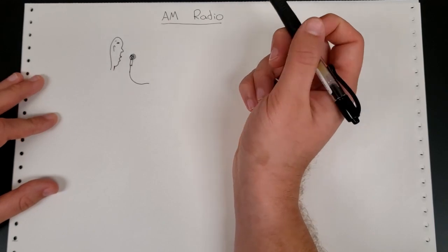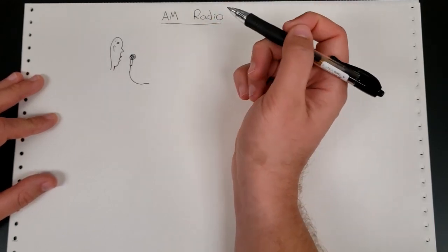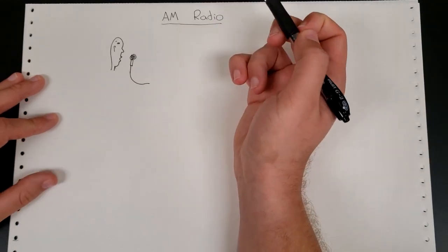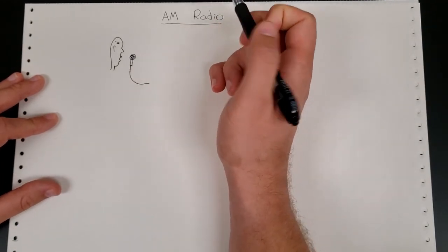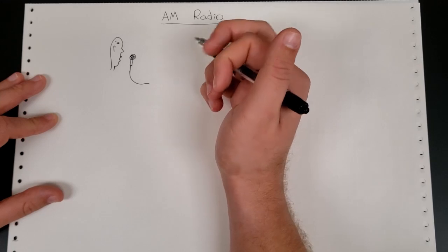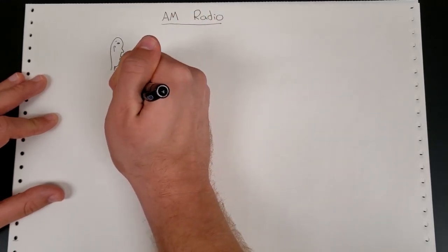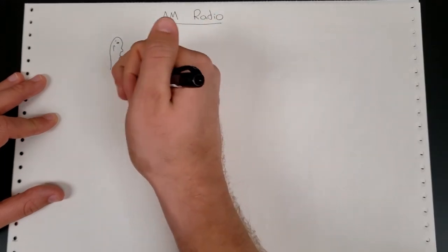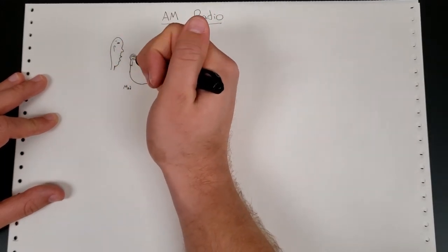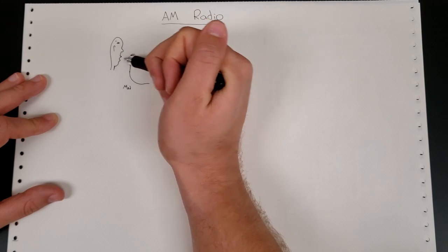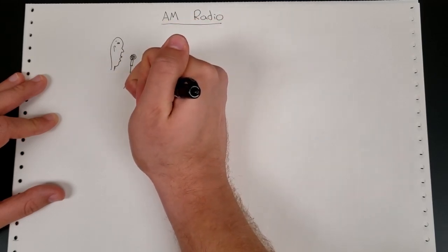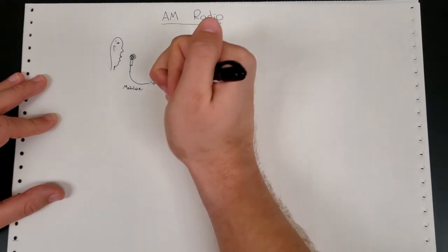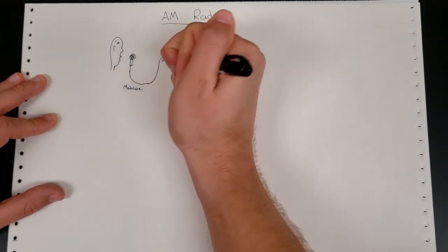Okay, so when we're trying to make sound waves travel over larger distances, we have to first convert them into electromagnetic waves, because electromagnetic waves attenuate much less in air, right? They can travel much further, and we have much less loss of power in the process. So it's a much more efficient process. So what we do is we do something called modulate. So our first step in this AM radio is we take whatever the small signal is, and we use it to modulate a carrier wave.